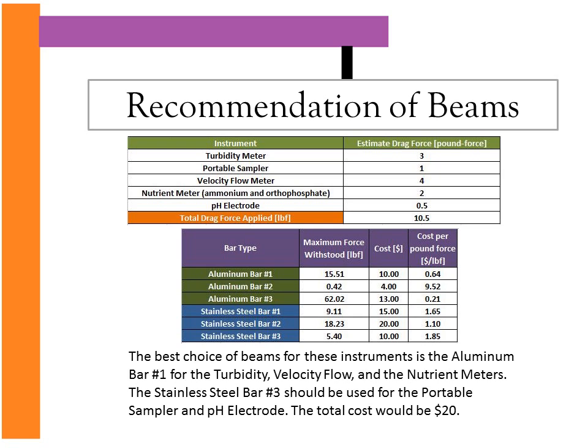We were given the requirements that only 3 instruments could be placed on a single beam, and the total deflection for the 5 total instruments could not exceed 1 inch. With all of this in mind, our goal was to fit these requirements in a cost-effective manner. Since only 3 instruments could be placed on a single beam, and the sum of the greatest 3 instruments' drag forces was 9 pounds force, we chose the cheapest beam that could withstand greater than this value.